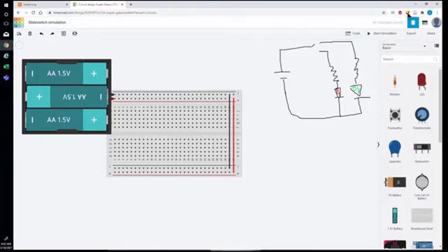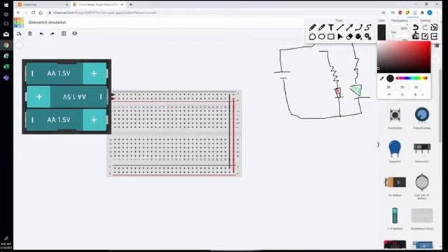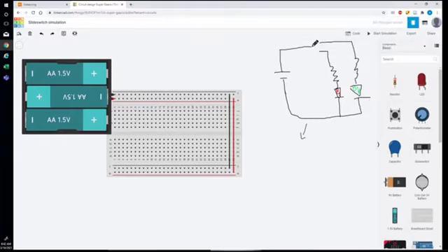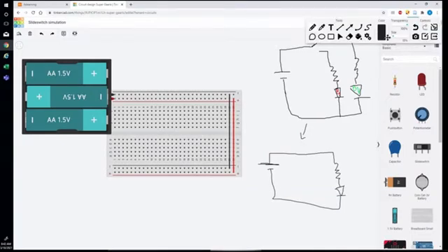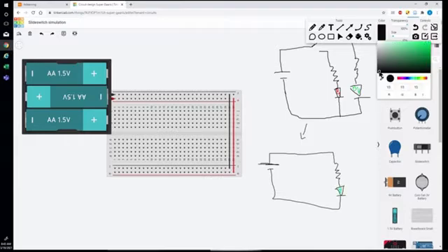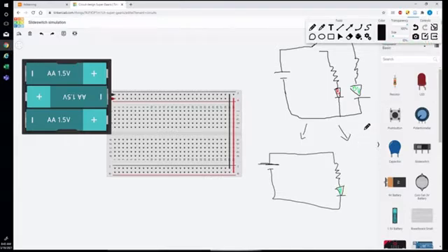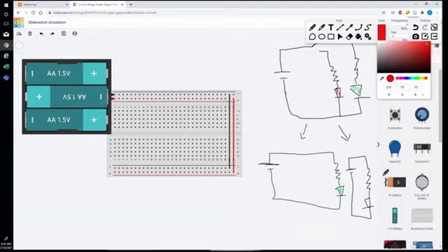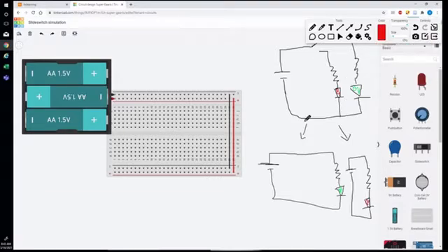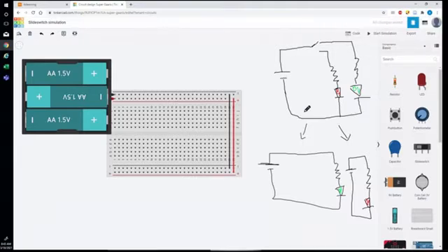When you think about this circuit, you can split this circuit up into 2. If your switch is selected in the position that the green LED is lit, then the circuit that you have looks like this. And this is just your regular series circuit with a green LED, nothing fancy. If you are in a situation where it's the red that's selected, your circuit is going to look like this. And this is going to be your red. So you're literally selecting between 2 circuits over here. Is this going through the green path? Is this going through the black path?